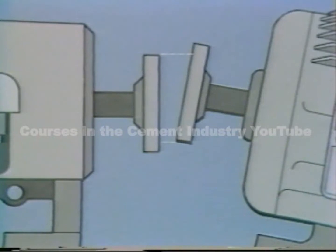One way of detecting this would be to measure the distance between the coupling halves at the top and at the bottom. If they're not equal, you have angular misalignment. In this case, the distance at the top is greater than the distance at the bottom. So we know we have a problem.